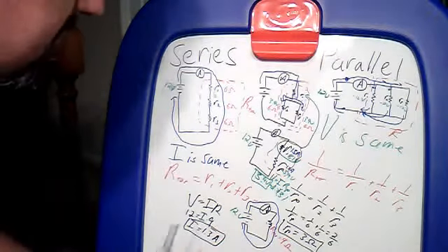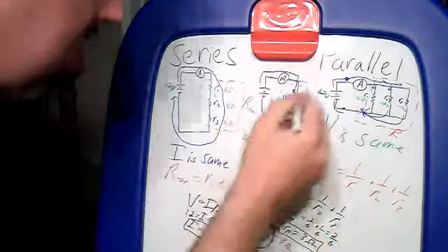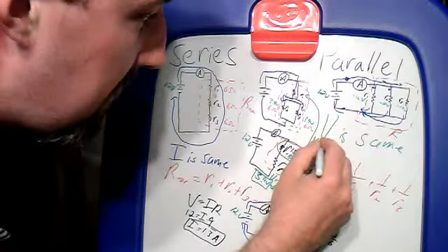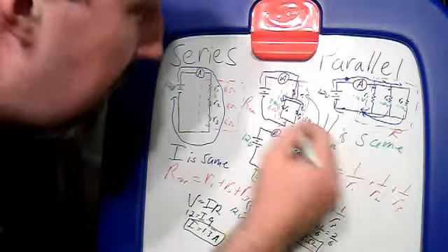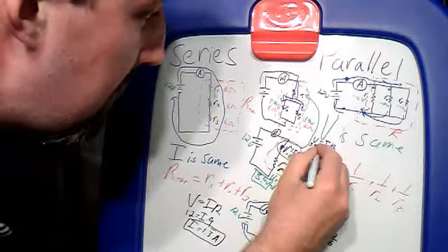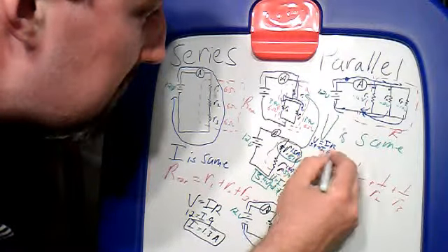And if we know these resistors are each 6 ohms, we can then figure out the current. So we could say Ohm's law again, and we're running out of room, so let's do it right over here. V equals IR, and we got a voltage drop of 3.9 equals current times 6 ohms.